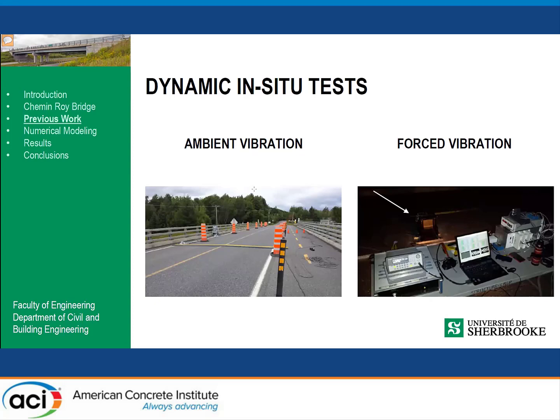The ambient vibration tests are easier. It's fast, it's quick to complete, and it allows for many recording stations. However, as you see on the right, force vibration tests with a small shaker were performed afterwards. It takes more time, but it is really more precise.